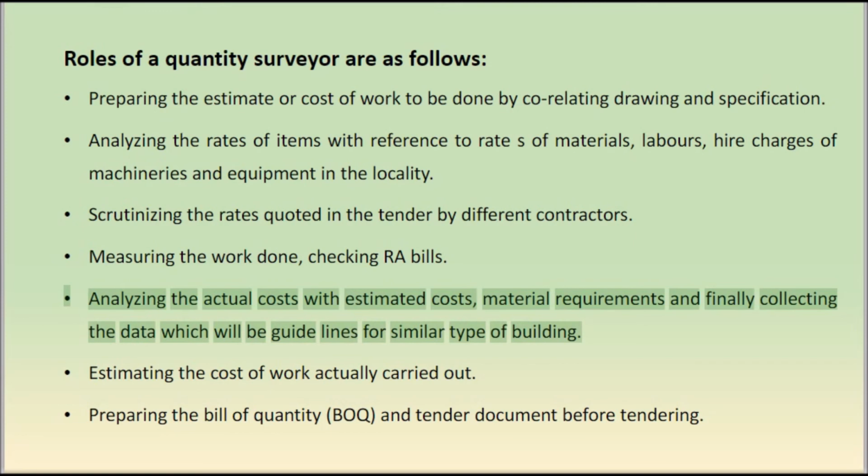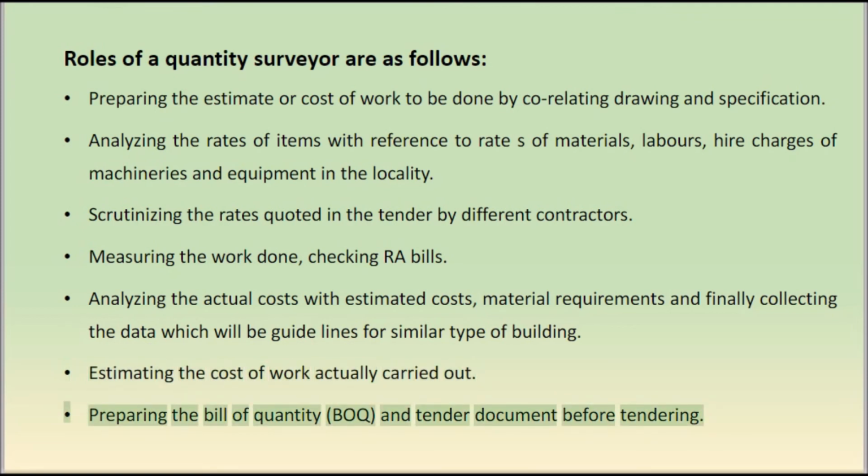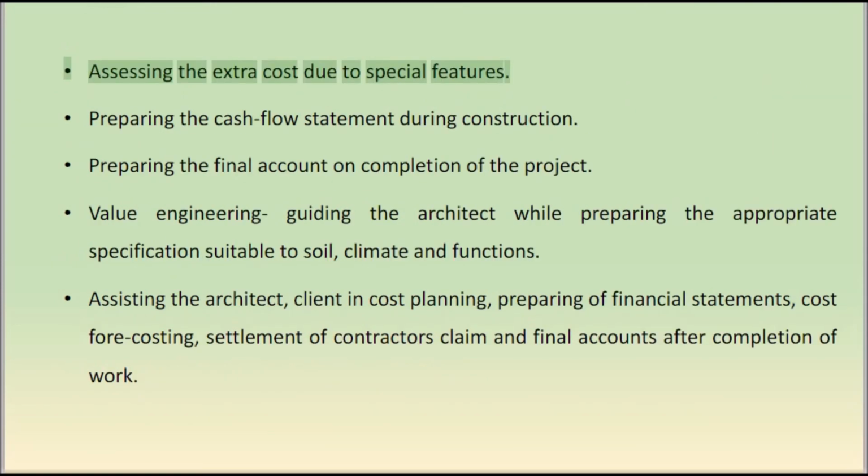Estimating the cost of work actually carried out. Preparing the bill of quantity, BOQ, and tender document before tendering. Assessing the extra cost due to special features. Preparing the cash flow statement during construction. Preparing the final account on completion of the project.